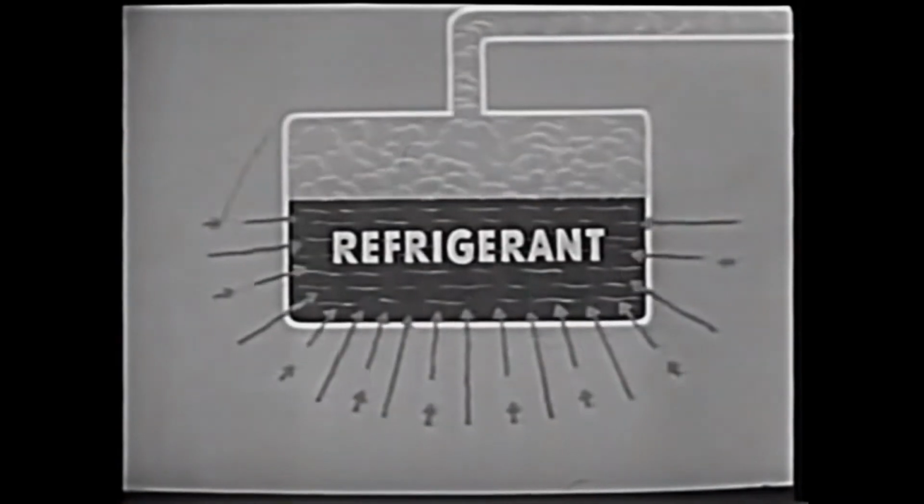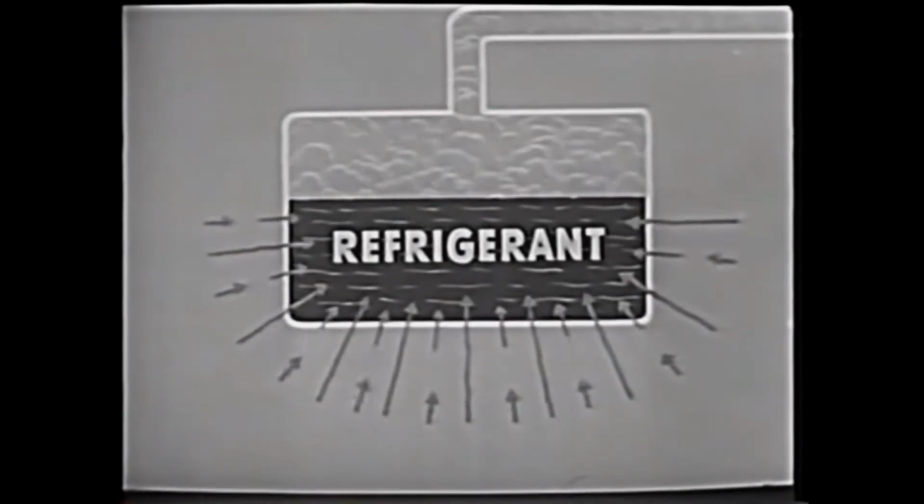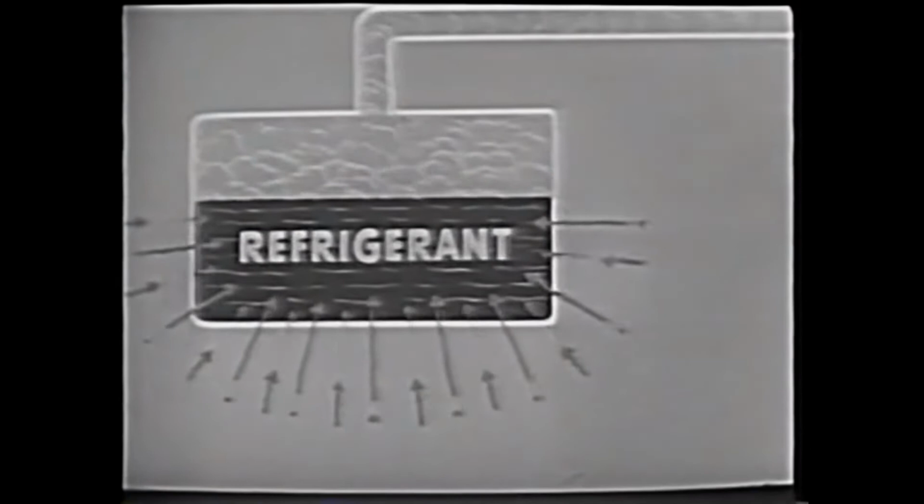The principles of refrigeration are physical principles applied as follows for the purpose of removing heat and reducing temperature. First, mechanical refrigeration rests on the ability of a refrigerant to absorb heat while changing from a liquid to a gas and to release that heat while returning to the liquid state.